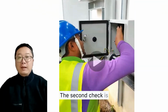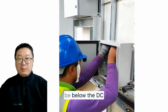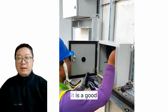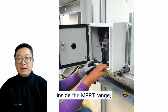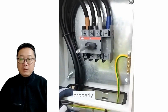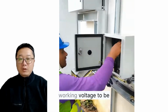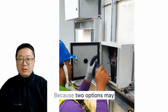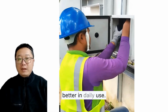The second check is the MPPT operating voltage range. A string may still be below the DC maximum limit, but that does not automatically mean it is a good design. If the string working voltage does not sit inside the MPPT range, the inverter cannot track and use the array properly. The third check is even more practical. I want the actual working voltage to be close to the inverter's better operating zone, because 2 options may both be allowed, but one can still perform better in daily use.